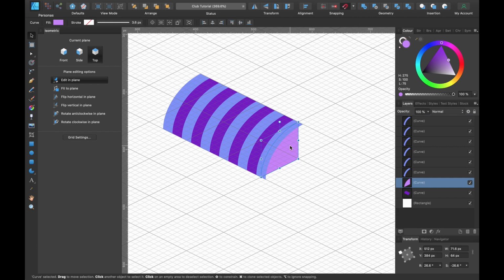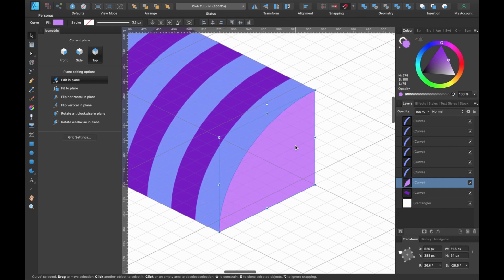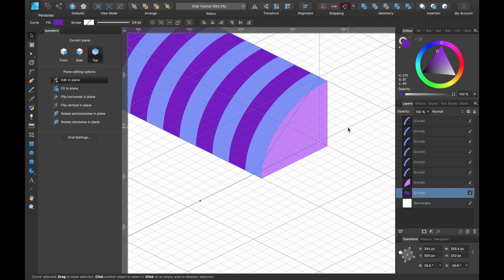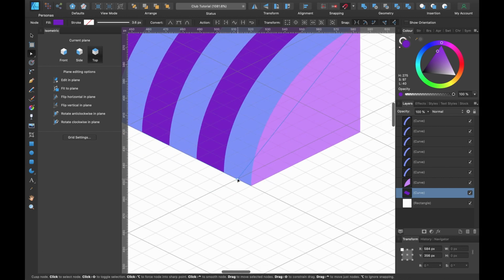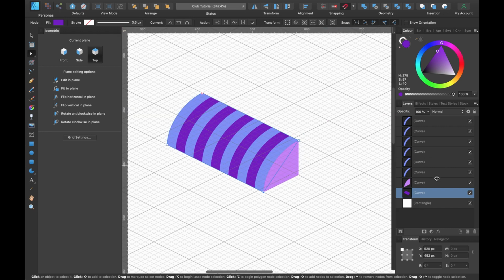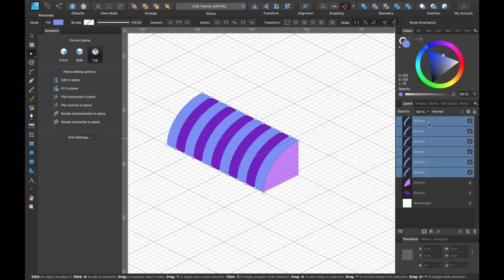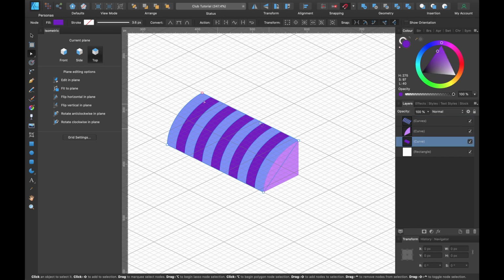Okay, now I'm just going to drag this shape just out a little bit till it meets up with this shape here. I'm just going to make sure underneath that that's also going to cover that whole area. So I'll just drag it out till it meets the points again. Okay, so with these shapes here, we're going to press geometry. We're going to press add so that they're all kind of one shape. And then we're going to nest it or clip it inside of our larger shape here. So I'm going to click on it, drag down and to the right, and now that's inside of that shape.